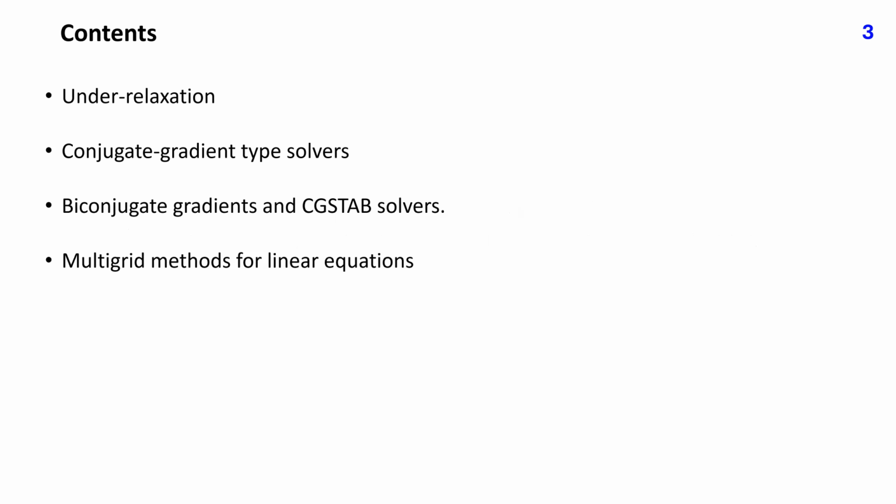In this lecture, we shall first discuss the under-relaxation approach. Its aim is to promote the convergence of outer iterations when solving nonlinear and coupled equation systems, but it is also important when deferred correction approach is used in conjunction with discretization methods of a high order. Because it modifies the linear algebraic equation system and thus influences also the performance of linear equation solvers, the under-relaxation approach, which is widely used in CFD, is described first.